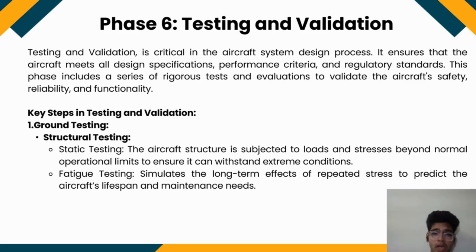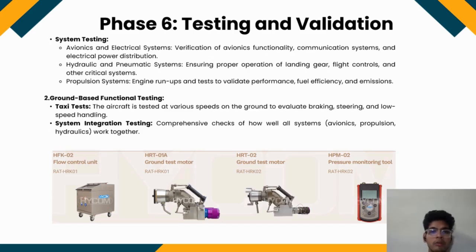After that, we move on to fatigue testing, which simulates the long-term effects of repeated stress over the aircraft's expected lifespan. By cycling the loads on the aircraft structure, we can predict how it will perform over the years of service and identify any potential weak points that might develop.